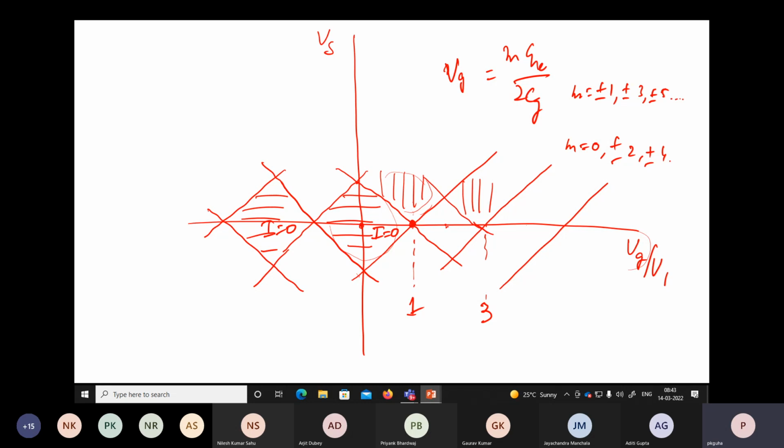But as you understand, there are a lot of constraints. You have to have a very small quantum dot with a very tiny junction, so that you can get a very small capacitor. This kind of fabrication is not easy to do, so it is not easy to batch fabricate these devices. It is difficult to have such reliable devices in large numbers, all performing in the same fashion. That is why there is no commercial device of such a type. But people have already demonstrated in their labs that it is possible to make such devices with a fair amount of accuracy and achieve this kind of characteristics.